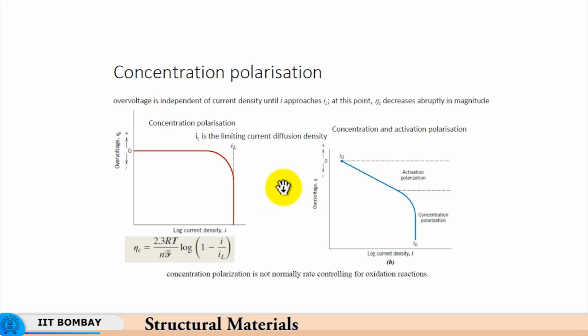or reduce the activation. So, supposing you want to deposit a coating onto a surface, then you need the surface to be reactive. So, you want to activate the surface, right, because for a coating to be deposited, you need to have a chemical reaction between the solution and the surface.